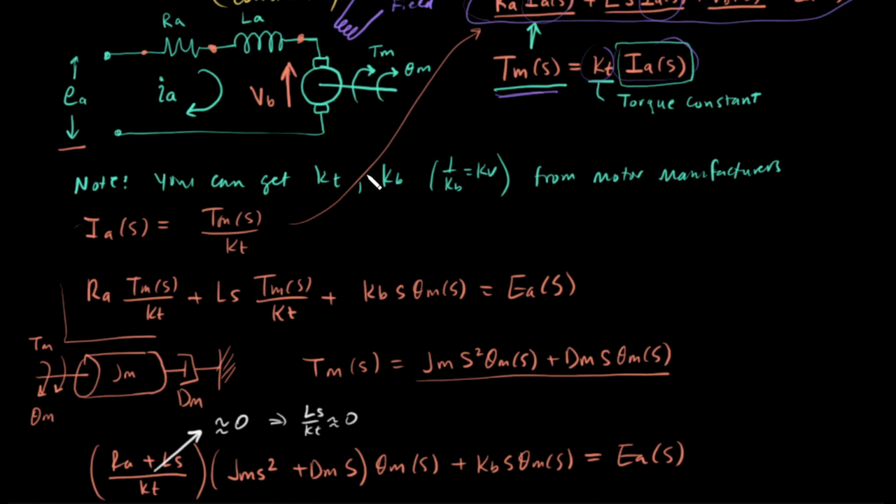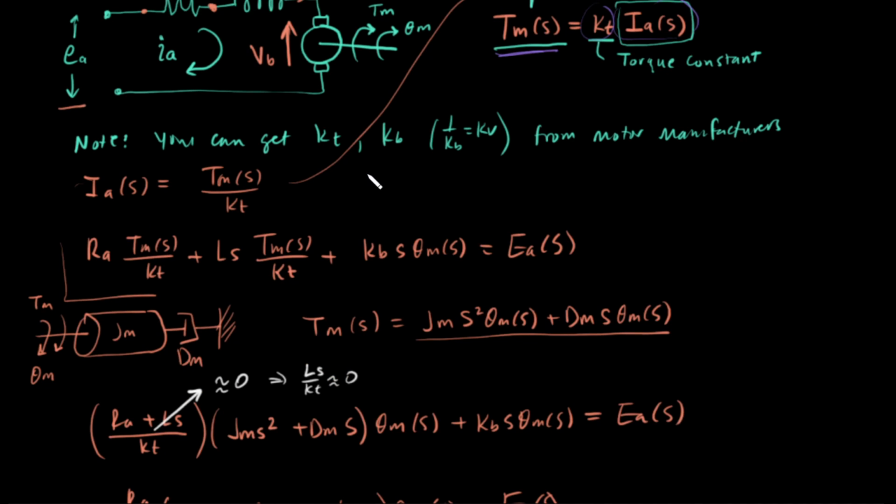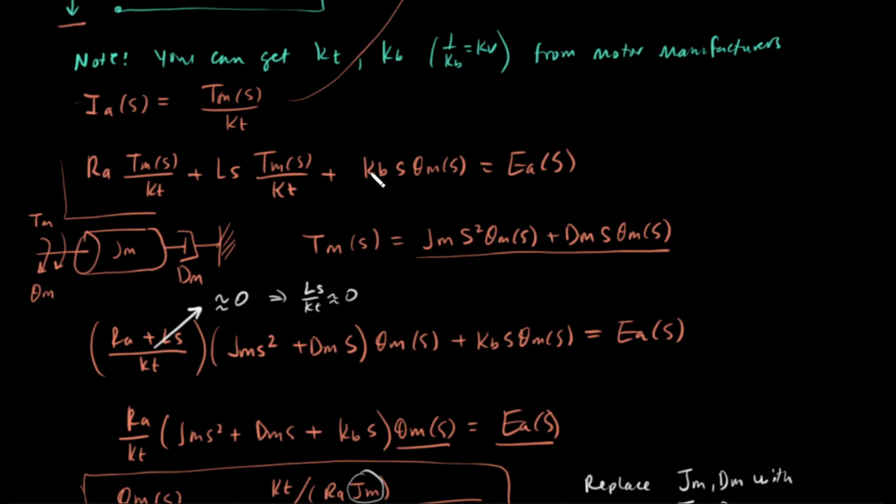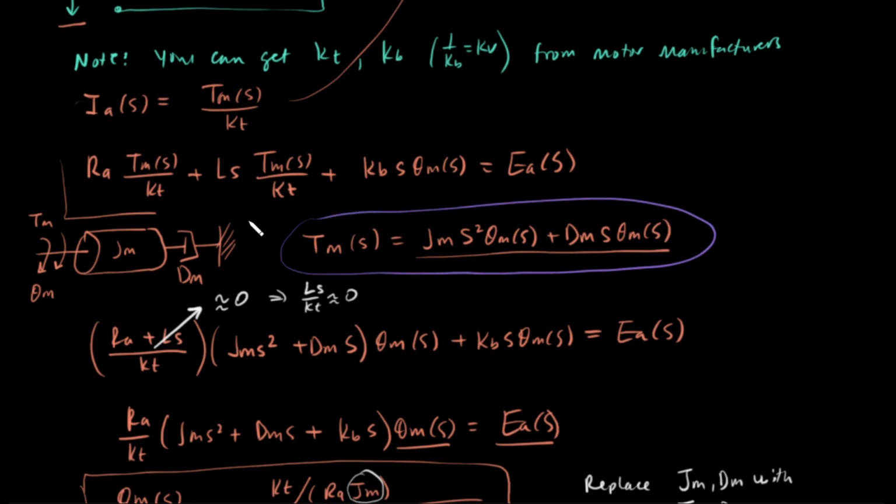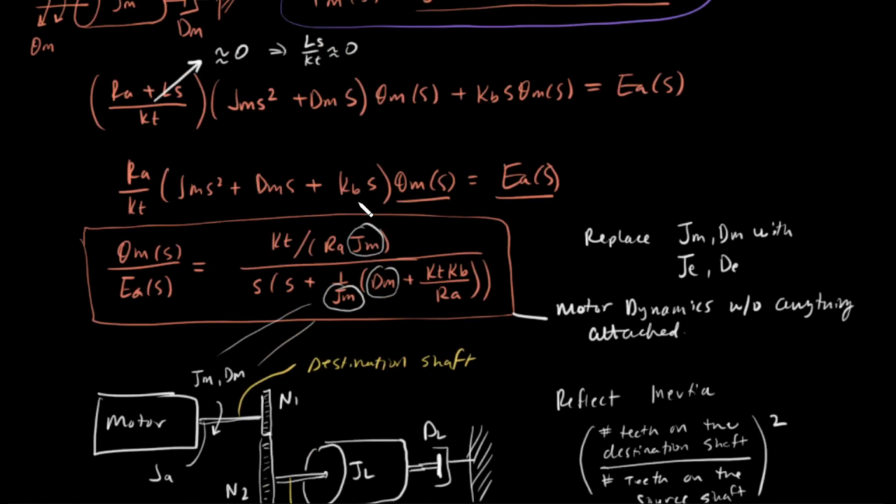We also know how to get the torque from the mechanical part of the system, and that's what we did here. We showed that this is the mechanical expression for torque, and so that allowed us to include the dynamics of the shaft into the electrical dynamics in the Laplace domain to get these expressions for a motor.